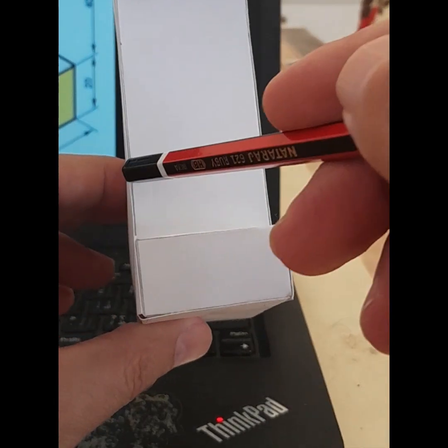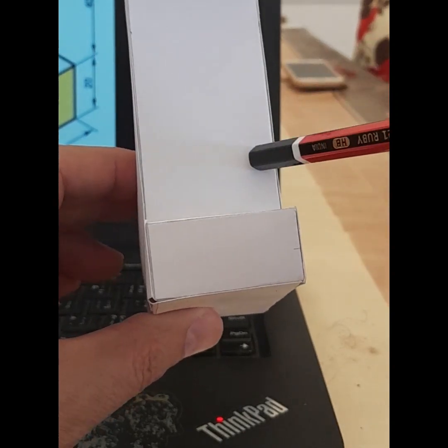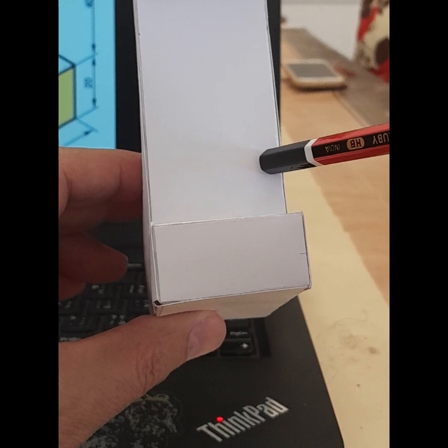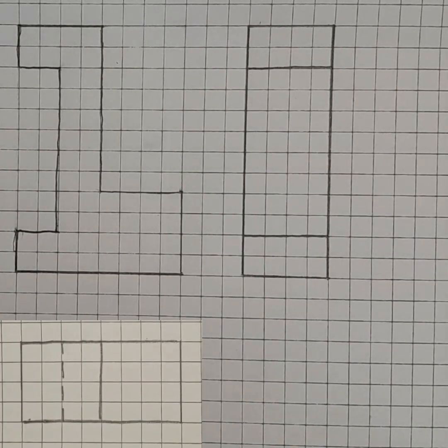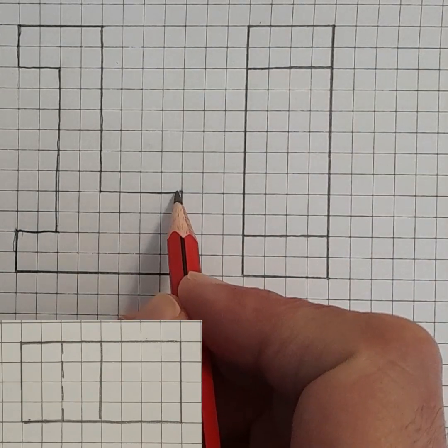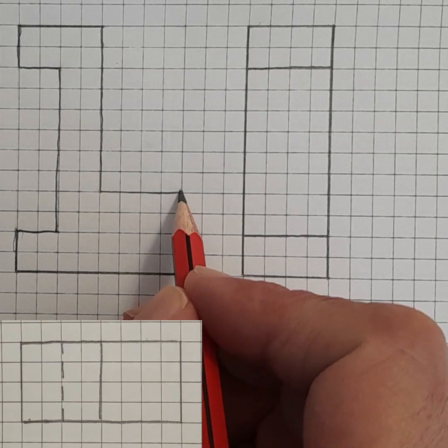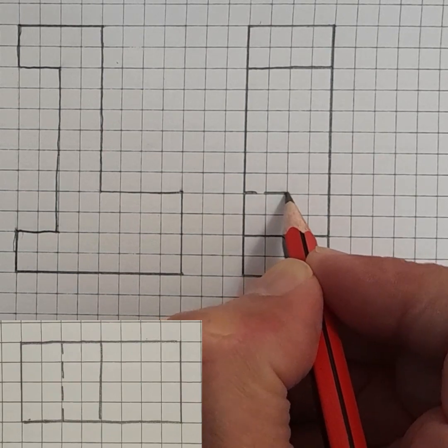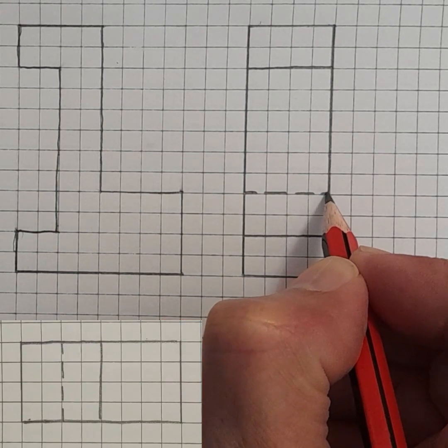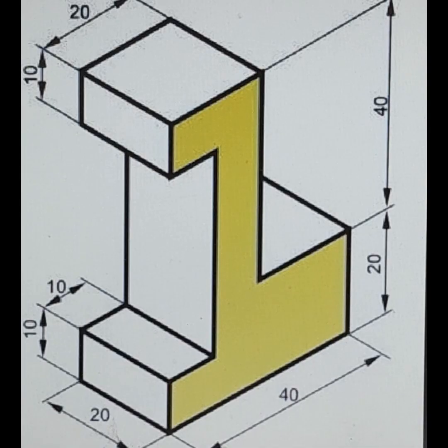So at this part, we have to draw a straight horizontal dashed line. It is not necessary to go to the drawing to know the dimension. The dashed line should be aligned with this surface. So aligned with this line or with this point, I will draw a horizontal dashed line like this. Now I completed the three views of this part.